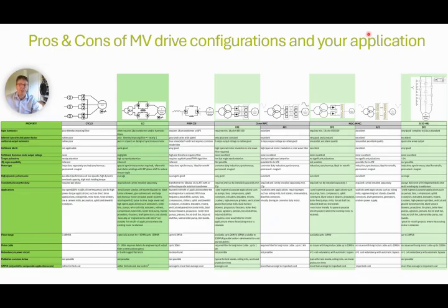Torque pulsations are significant in the Cycloconverter and in the load commutated inverter, even up to 8% in the case of a 12 pulse LCI. Depending on the drive machine, analysis might be recommended for the other topologies. It makes sense to validate the simulation results with real measurements.